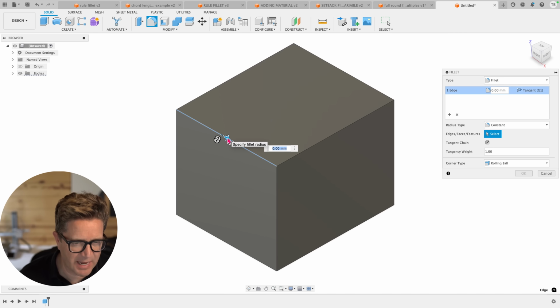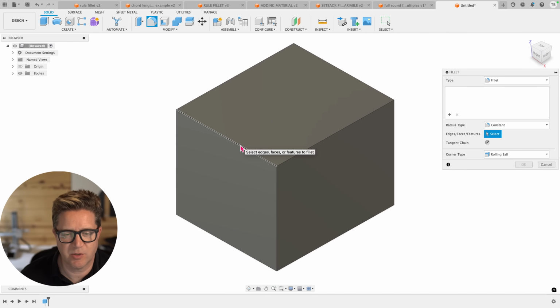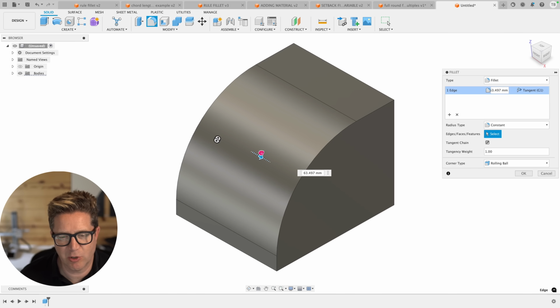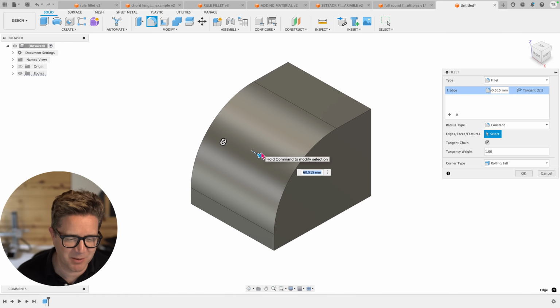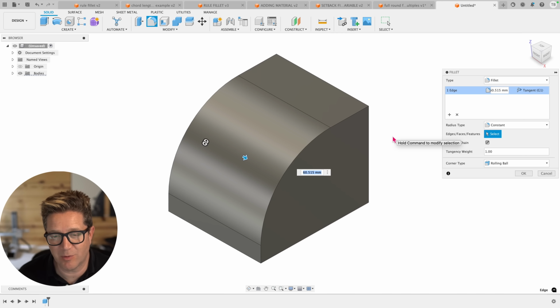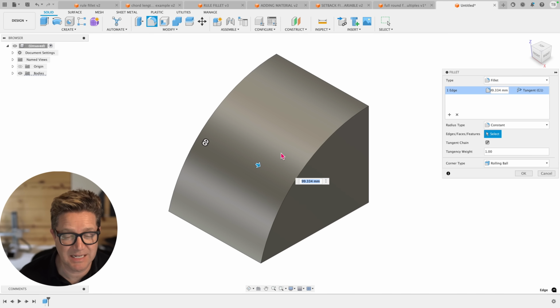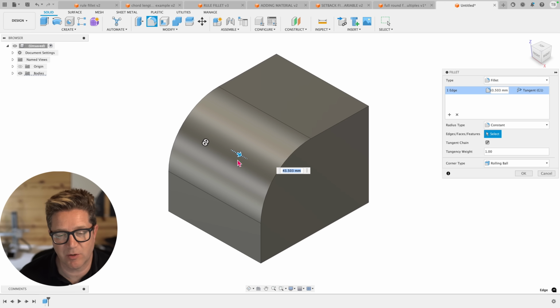And there's a handle or dialog here. We're going to choose this edge, and you can drag this handle and create a huge fillet. And this is my first tip: fillets don't have to be really simple, small finishing touches. They can actually make significant changes to your model if you want them to. On the right here, constant is probably going to be the one you're going to use the most often, and it's going to be helpful for creating this consistently round fillet.